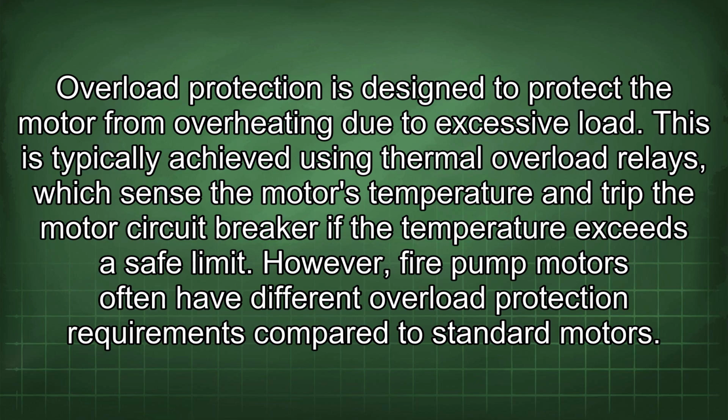Overload protection is designed to protect the motor from overheating due to excessive load. This is typically achieved using thermal overload relays, which sense the motor's temperature and trip the motor circuit breaker if the temperature exceeds a safe limit. However, fire pump motors often have different overload protection requirements compared to standard motors.